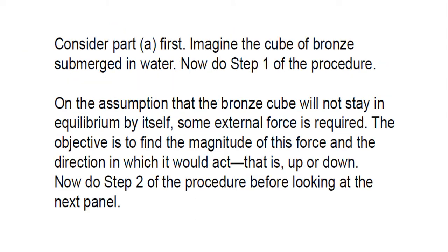Okay, so we go through this one by one. Start from this note. Now we consider part A first, completely submerged in water. You have to draw your FBD of that cube and label all the forces acting on the cube. On the assumption that the bronze cube will not stay in equilibrium by itself, some external force is required.